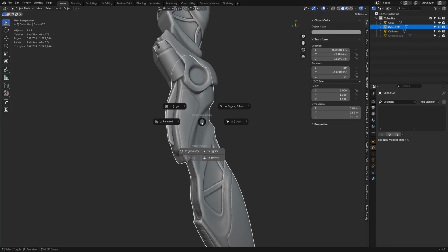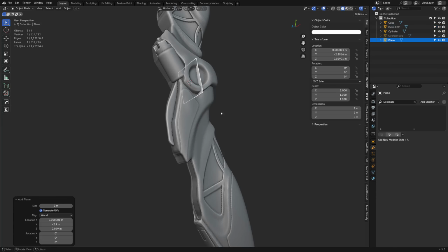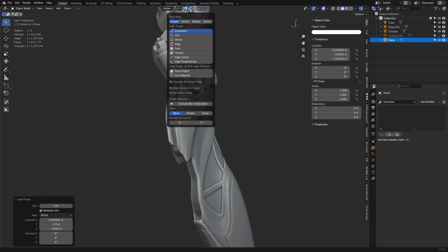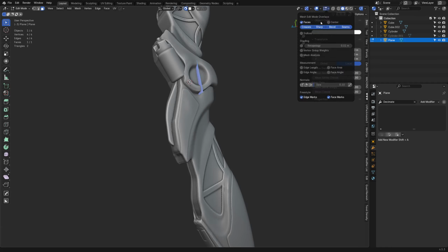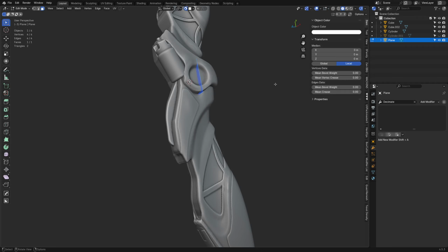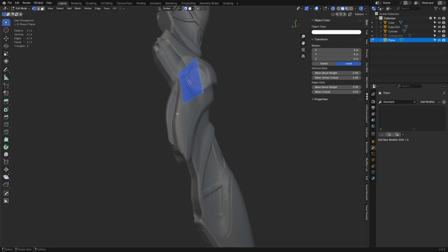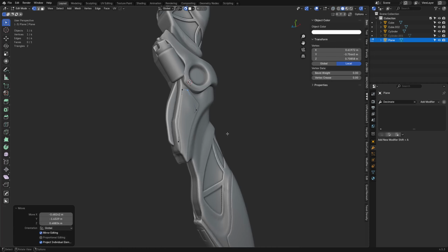But the next step, of course, is going to be creating a plane, turning on snapping or face project. You can turn backface culling on, and maybe leave the line rotation target off for now. When we're in edit mode, we can do retopology shading. Go into vertex, hit Alt Z, machine tools. So we're in edit mode now. This is going to start working onto the surface.